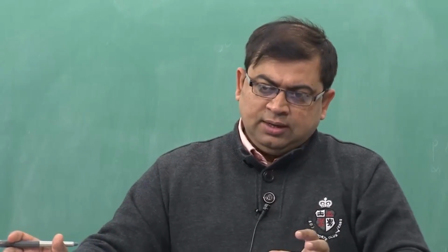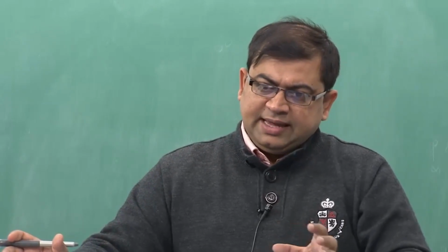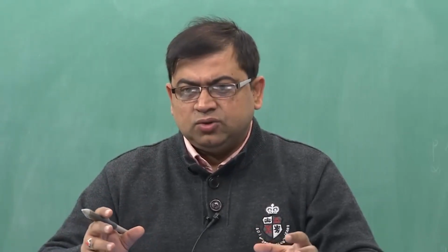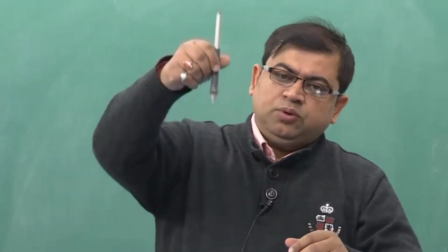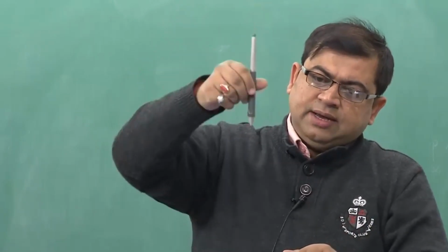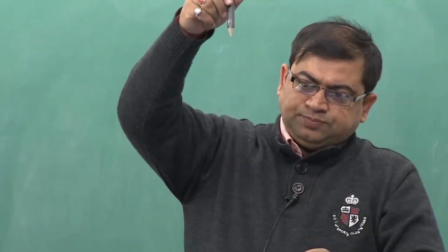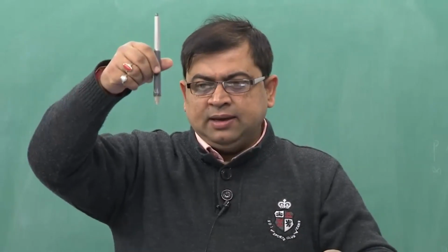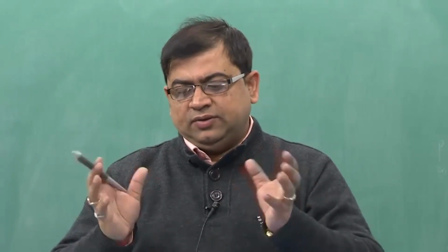And so, if we can utilize this clinging to the surface phenomenon based on the various speeds of rotation or the dwell times, because on one hand you are pulling the seed out, so you are trying to bring it to a lower temperature, so solidification would start happening, and on the other hand you are trying to limit the amount of dwell time by increasing the rotation speed of the crucible.